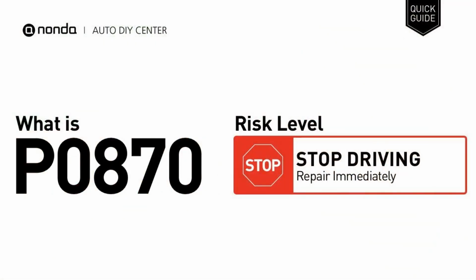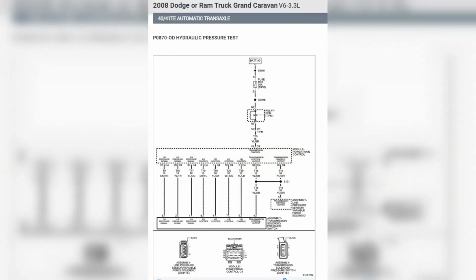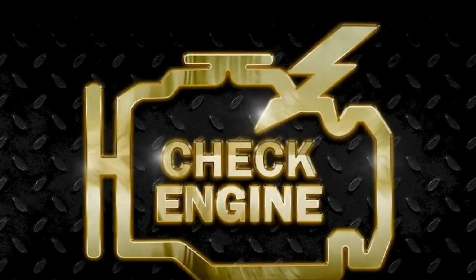The technician should also watch the freeze frame to determine when and where, in the order of events, the code was set. Once they've checked the transmission, they can reset the error codes and test the vehicle to see if the code reappears. The technician will use the scanner to diagnose electrical problems with the system and examine the wiring, repairing and replacing components if necessary. Disconnecting the electrical connector and testing the sensor voltage is also part of the process, and if it fails to comply, it may need to be replaced.